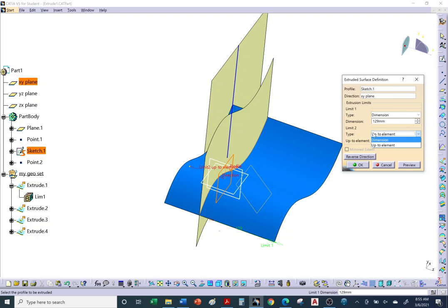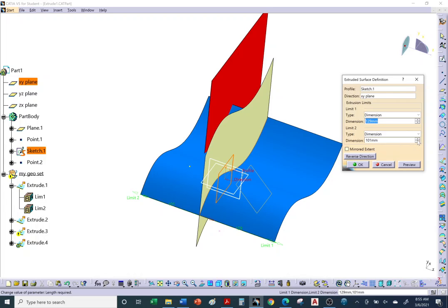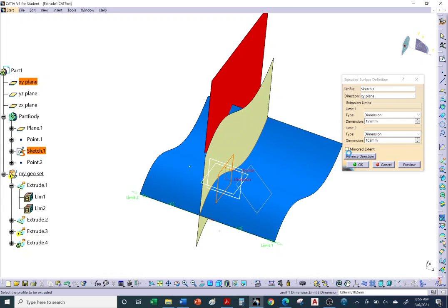Let me go back. So I was supposed to do this side. Dimension. And I increase it. Oh, it's having trouble finding that point. That's okay. So I'm going to increase it by 200. The point is having trouble updating. And this does happen with vertices when you borrow a corner. I forgot to mention that. Let's go to 200 in length.